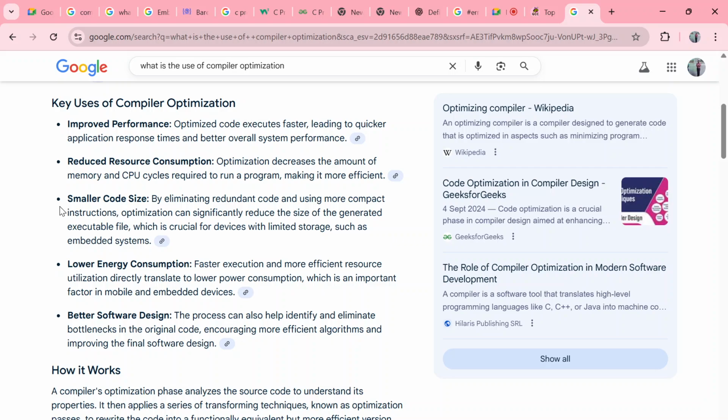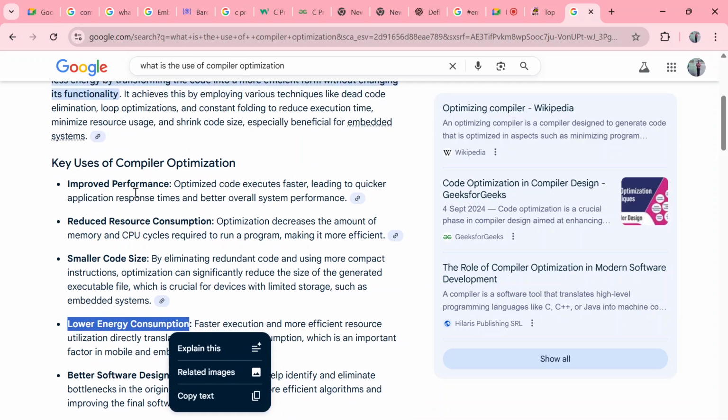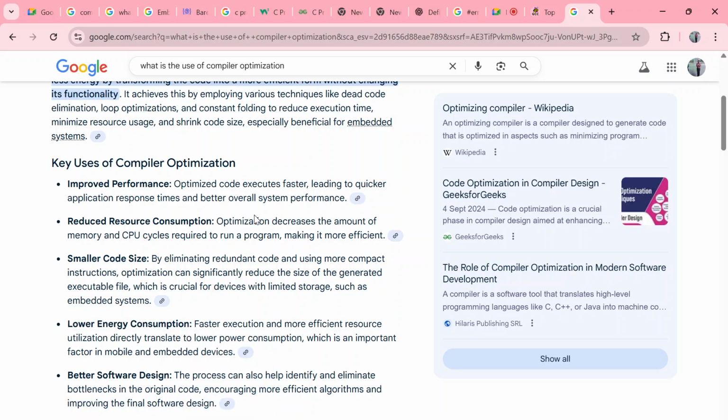Storage, you are reducing the instruction size, which means the memory efficiency is increased. And also, if you are executing only 5 lines, less power is going to be taken. So it's considering low power consumption, everything is coming under optimization, it will take care. The main key is that it's reducing the instructions, which the optimization suspects are unnecessary.